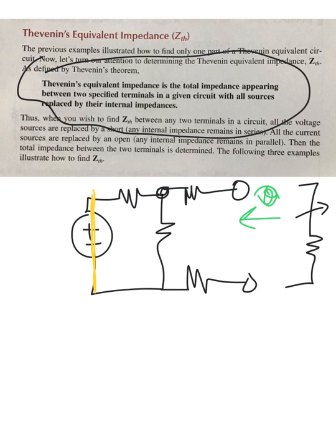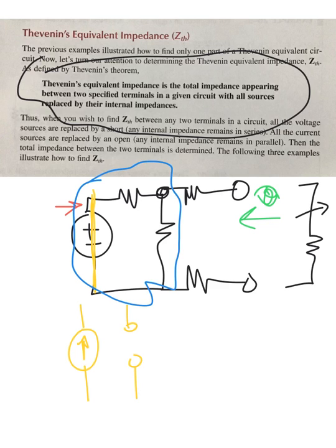And if it was a current source, you would open the current source, making the circuit easier. You look in and you start compressing from the left side forward. Right where the power supply used to be is a wire. So, in this problem, you would grab these two in parallel, and then they would combine to form a bigger series circuit, and you would have Thevenin.